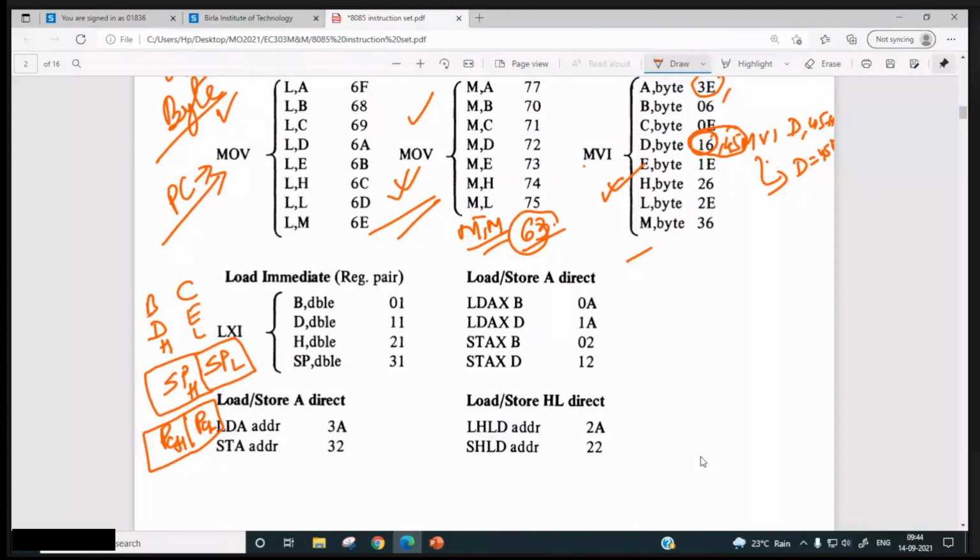So what exactly is this instruction going to do? Sir, it will store the value. If BC is there, sir, in the BC register pair we have a memory location. So that memory location you tell me first. BC register pair, you tell me the memory location so that I will write over here. Sir, I need 2401H. Right.